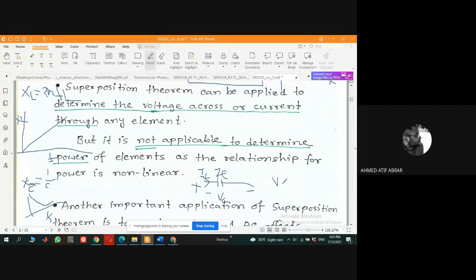So VC by ZC, right? Because VC is the voltage across the capacitor, we write VC divided by ZC, and that has to be equal to the current, which we denote by IC. Please excuse my handwriting, because I'm not using the pen once again. So if I rearrange this relation, could I write VC equal to IC times ZC?